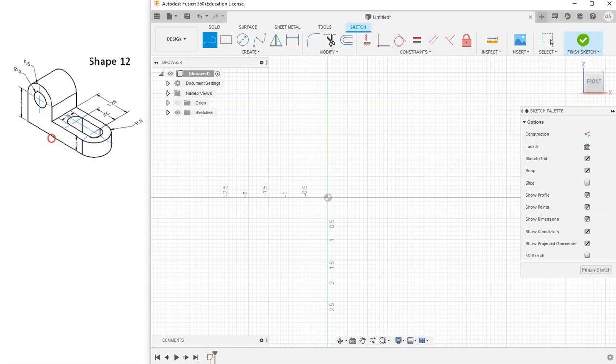And it doesn't actually tell us that dimension. We can figure it out though using a little bit of math. So if we look from this edge over to this edge, that's 1.25. If we follow this edge through the center mark to our extension lines, all the way through our dimension line into this edge over here, this is 1.25. And so hopefully that's obvious.